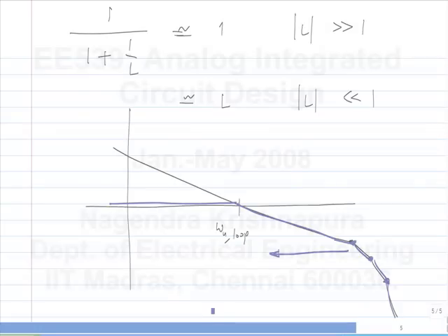So in that case, you come up with approximate criteria like phase margin. You first do an analysis for a second order system and then you somehow relate it to the others as well. But again, if the parasitic poles are very far from unity gain frequency, we already know that the phase margin will be 90 degrees. So we say that if the phase margin is close to 90 degrees, you are very safe. Maybe 60 degrees and above is okay.